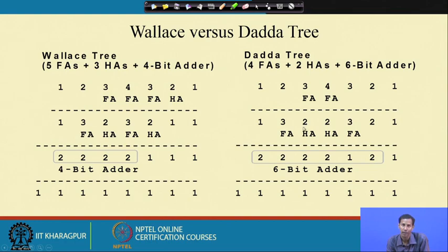So that will produce 2. So, 2 produces 1, and the carry from the other level, 2, sorry. Then 3 consumed produces 1, and the carry from the previous level, so that will produce 2. So 1 here, and the carry propagated from the previous stage, that becomes 2. So now this 2, 2, 2, 2, 1 and 2, I need to use a 6-bit carry propagator. Now I will get the corresponding results.